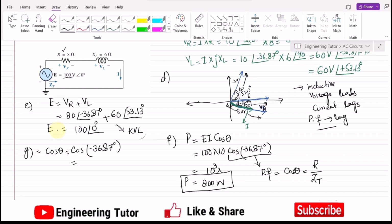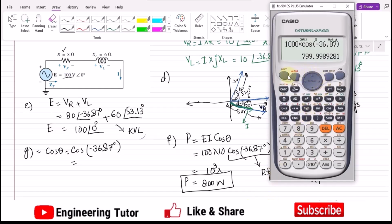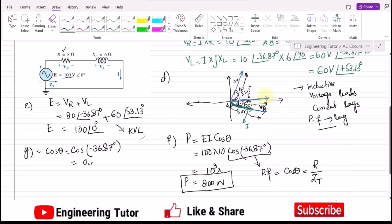Let me calculate it. Cos of minus 36.87, how much is it? That is almost 0.8. As the circuit here is inductive, and I have told you that in any inductive circuit the current lags, therefore this power factor is a lagging power factor.